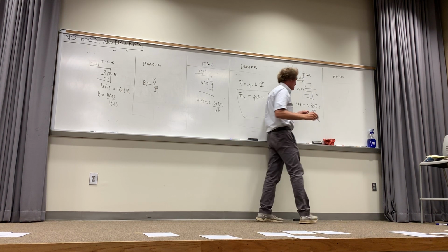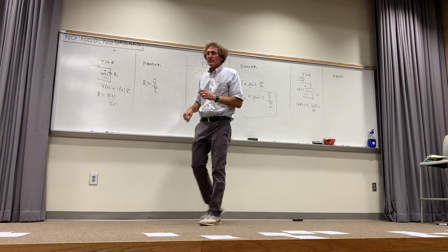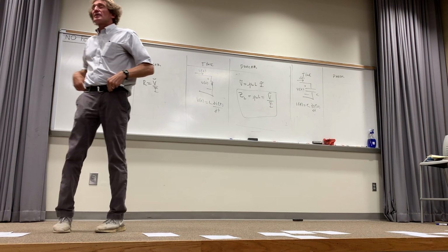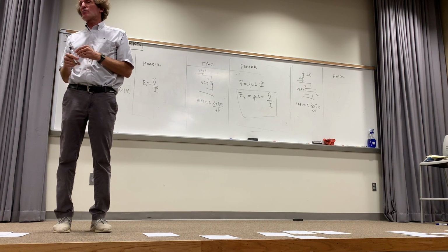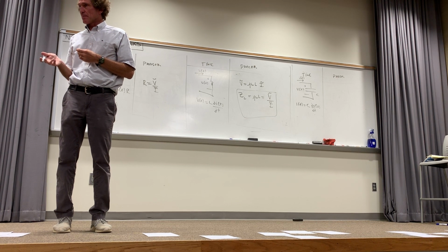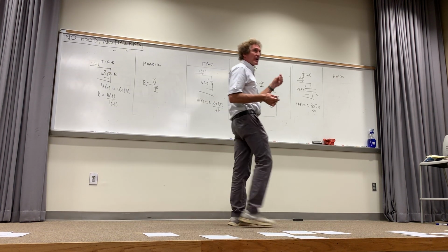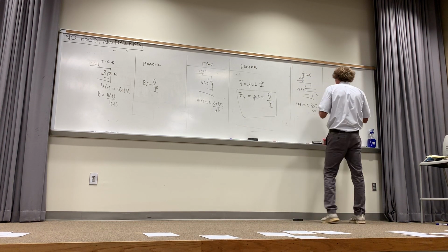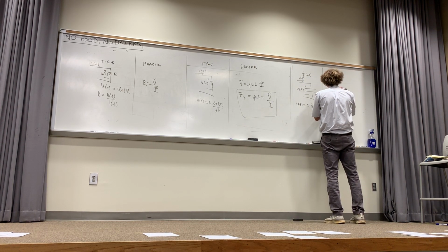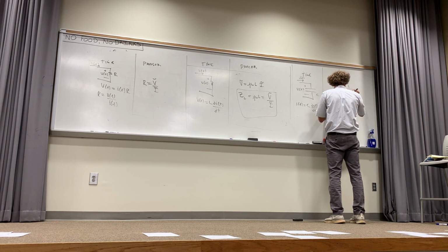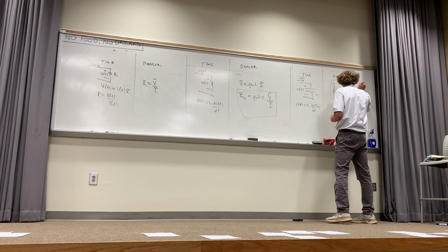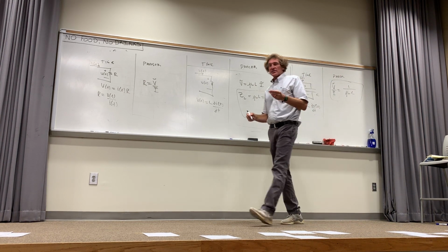That was the differential relationship between current and voltage in the time domain for any kind of transient behavior, right? We just did this. In the phasor domain, it's really nice. The relationship from V phasor to I phasor for a capacitor is just 1 over j omega C. And that is like an AC resistance.